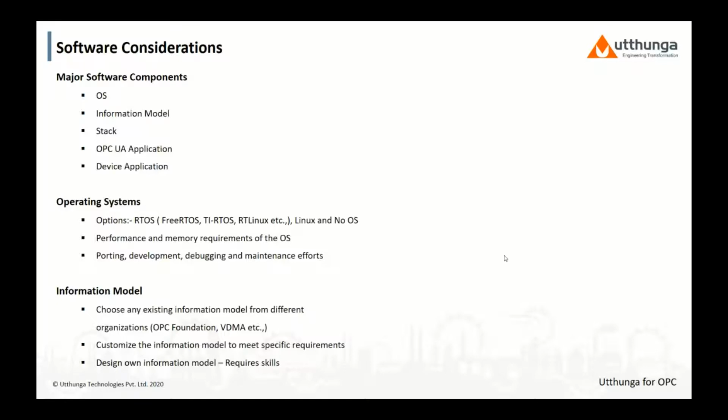Based on your hardware configuration, whether this is going to match. Do you have enough room for your application development, as well as stack porting and so on? With respect to that, you need to look at the memory requirements of the operating system. There will also be some effort on porting the stack, porting the specific OS to your target, development, debugging, and maintenance efforts.